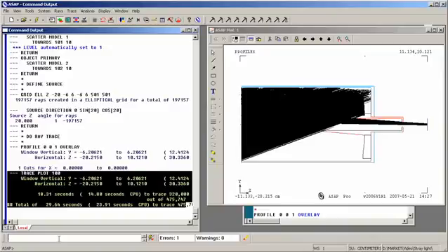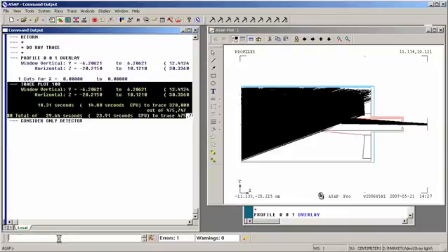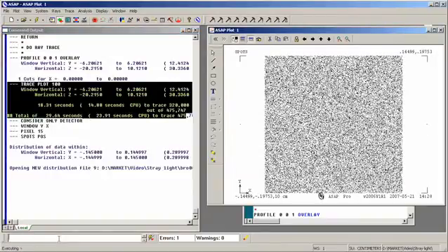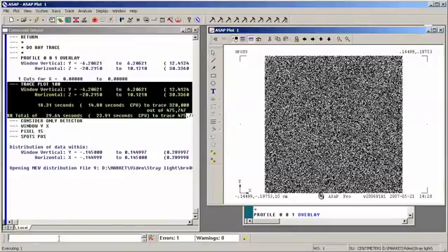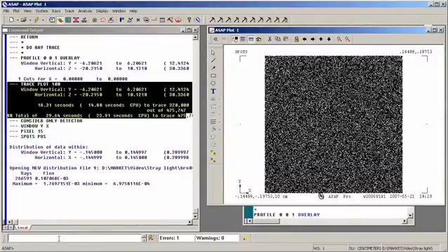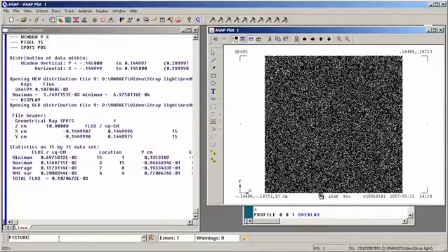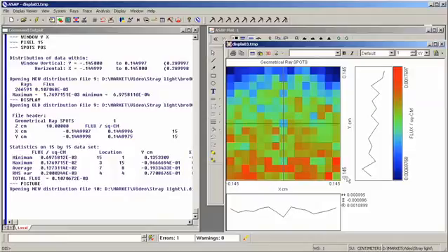Okay, we can now do exactly as we did before to calculate what the stray light irradiance is. Consider only detector, window yx, that's the size or dimensions or axes of our window. Pixel 15 is the resolution of our plot. Spot's position gives us our spot diagram and also calculates the stray light irradiance. The display command reads the file, and the picture command makes a picture of it. And so this is our stray light irradiance on the detector.